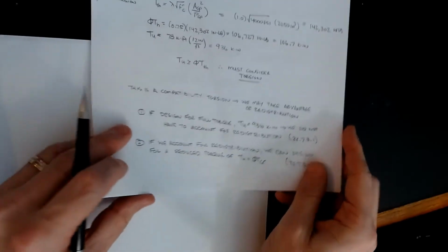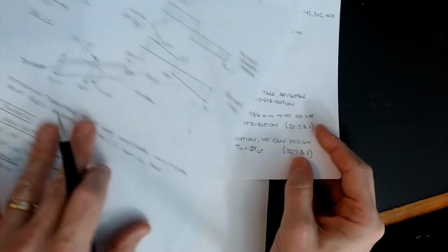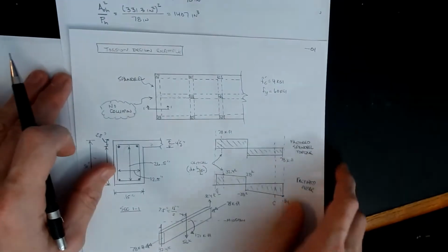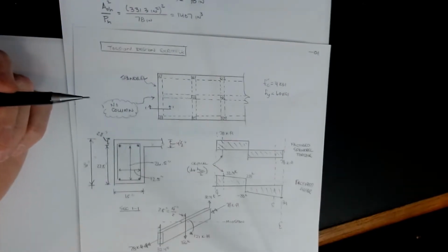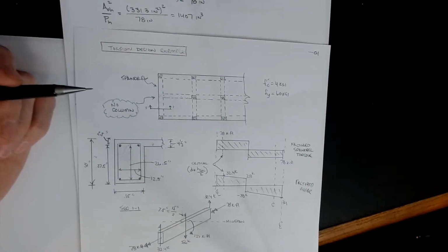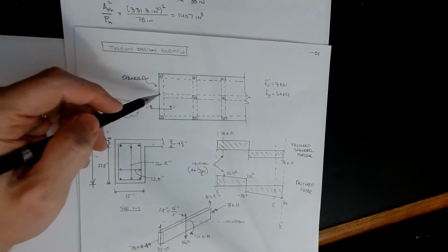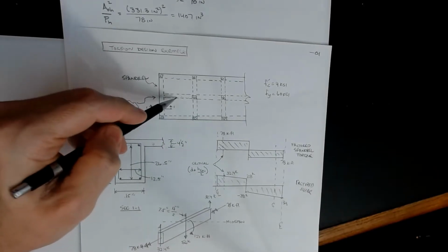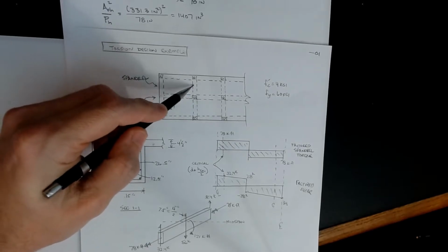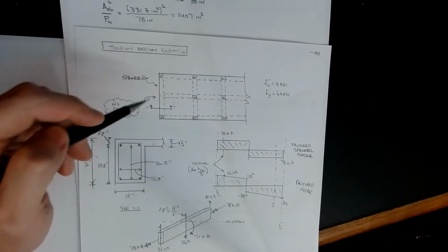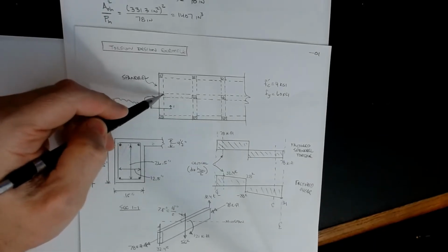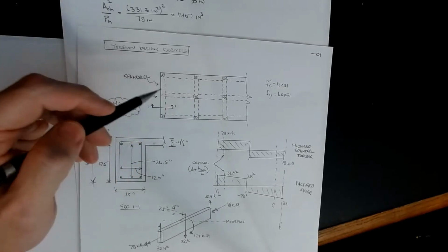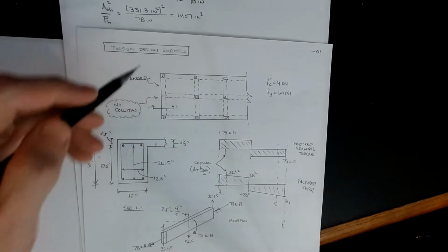Now, one thing that we notice about this beam is, if we go back and look at our framing diagram, we've got to figure out whether this is equilibrium torsion or compatibility torsion. The behavior of this is affected by the beam, which is affected by the column, which is affected by the beam and the slab and everything else. This is a compatibility torsion case, because if I allow this to crack and rotate, it will redistribute load over to other parts of the structure. So we're going to look at